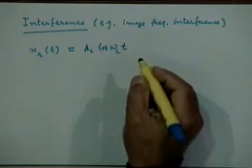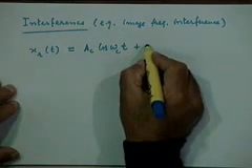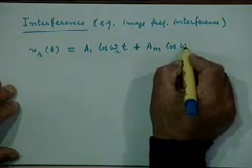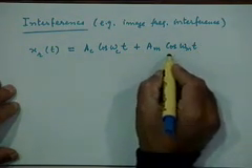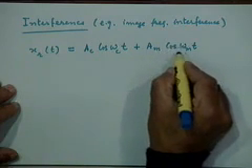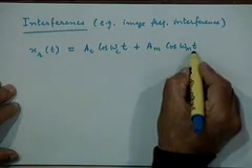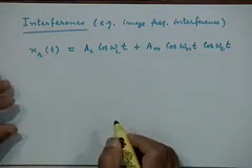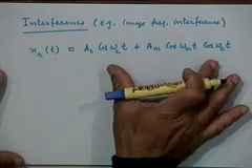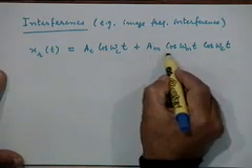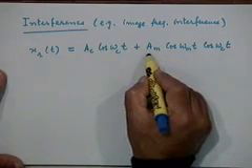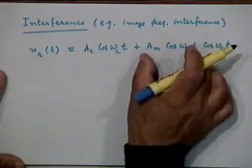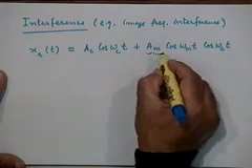the carrier of interest. It contains the modulated signal of interest, and for the purpose of discussion here I am taking the modulated signal to be A_m cosine omega_m t. So this is A_m cosine omega_m t into cosine omega_c t. These two are the desired components, out of which eventually I want to get, at the envelope detector output, A_m cosine omega_m t. I want something proportional to the message signal. I am taking this to be the message signal m(t),